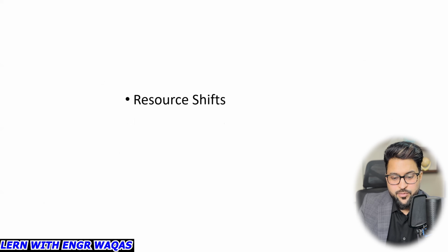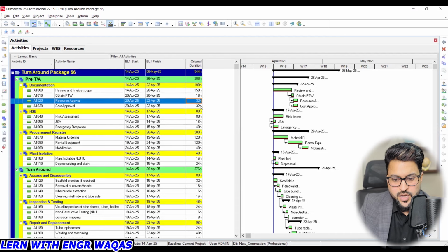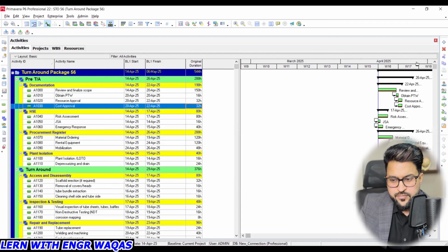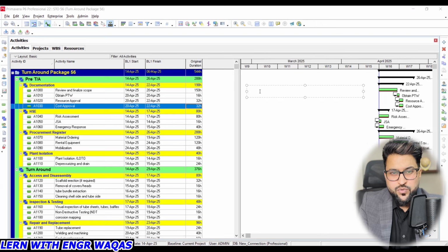So that is what I am going to share with you right now, the Primavera P6 dashboard, where I have allocated all of these 150 hours, 16 hours, 32 hours. This is actually your project total man hours required to complete that certain task. You understand? And usually benchmarking the previous data is going to play a very important role, and you can make a productivity goal as well that I am going to deal with specific gate valve maintenance. So benchmarking is going to help you: opening that nut and bolt on the gate valve will require maybe 30 minutes, or half an hour, like you can say 1 hour.